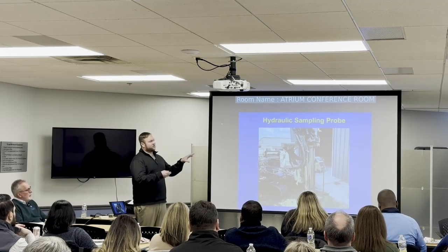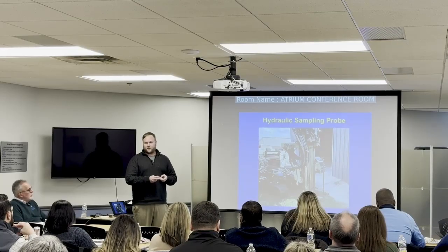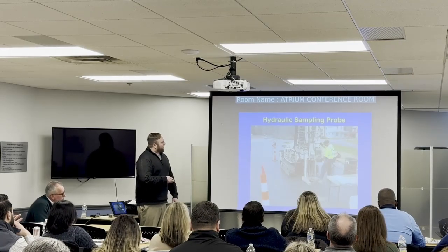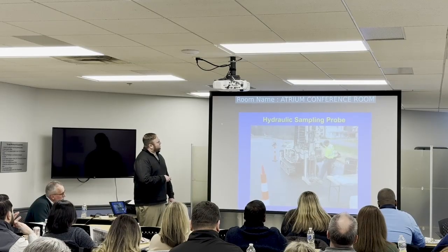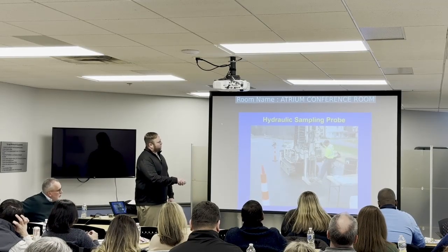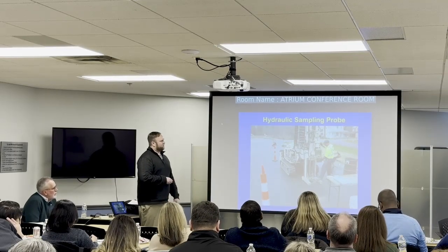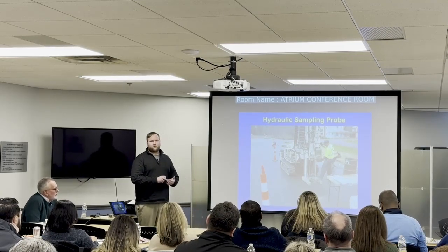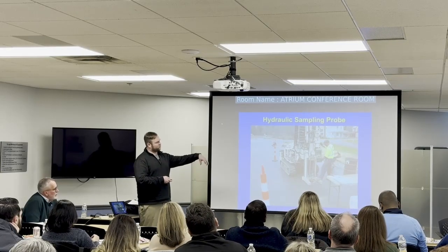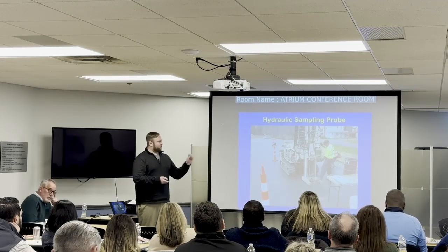Sometimes we do all of these in conjunction with each other. We might collect soil and groundwater and indoor air for some slabs, so it just depends upon what that risk item is. Here we're doing, again, some hydraulic probe sampling, but the one thing I wanted to point out, we're generating some soil spoils here. They have to be drummed up. Typically for phase twos, we don't install permanent wells at sites, which is the cause for that soil to come up like that. Generally, once we're done, you plug the hole and you go.